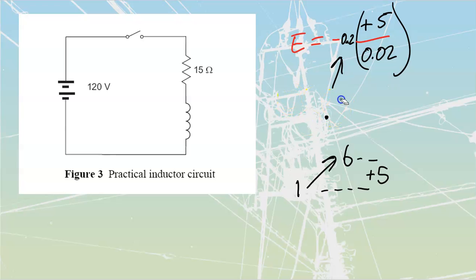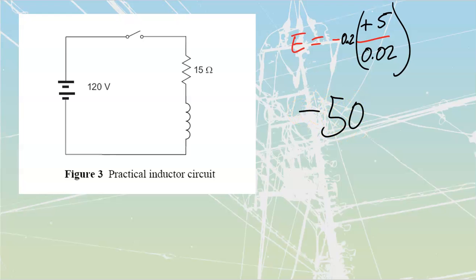And when you do that, you're going to come out to a value of negative 50 volts. I want you to take a look at that negative symbol that you're seeing off of that 50 volts. That negative is on there for a reason. It's because it is in opposition to my current flow. It was a raising value of current. Once again, we'll go to that little graph that we drew before. At this point, we were at a value of 1 amp, and then we bumped this thing up. When we bumped it up, we then get current that is in opposition to our main current. That's our main current. We're going to get opposition. That's why we got this negative, just showing that it's a counter EMF that's pushing back against it. It's the little linebacker. It is going to be defeated. It's a given thing, but it's going to slow it down a little bit.